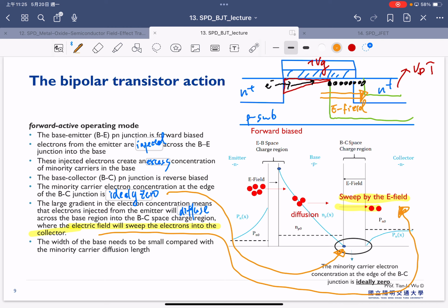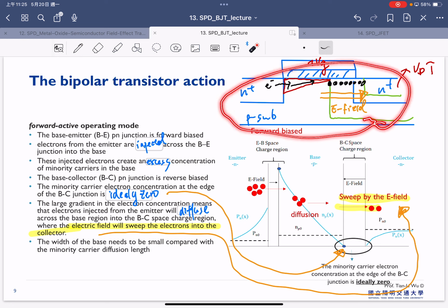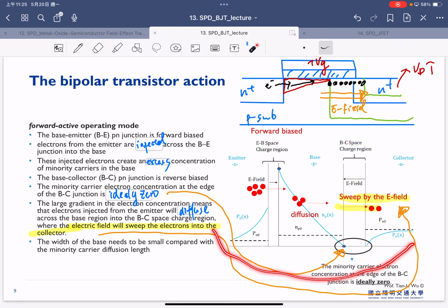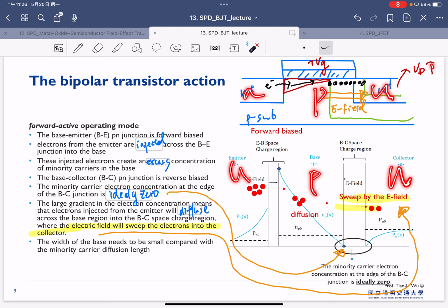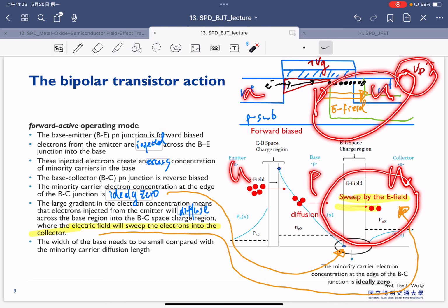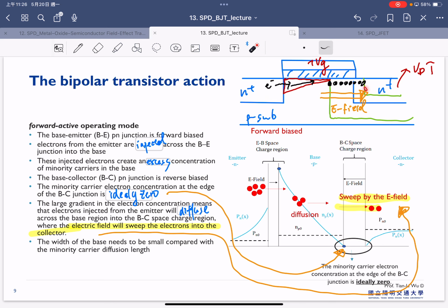So now you see, actually the operation of the MOSFET in this condition is exactly similar to this one, because first of all, we still have the NPN in here. Sorry, this is NPN. So that's the NPN here. And also under the large drain bias, we have the extension of the reverse bias, the extension of the depletion region, the same as here. So we expect there's a high electric field in this region.